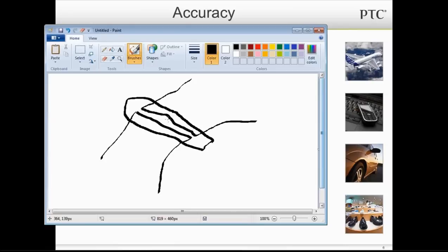And if you haven't noticed, for anybody out there that's a sheet metal guy, and I'll show you this on the slide here, at one point in time, and even now, I should say, the default accuracy that ProEngineer comes in is something called relative accuracy, and they're starting to switch that now to where the sheet metal templates start out in something called absolute accuracy, and I'll show you that as soon as we get back to our slides.